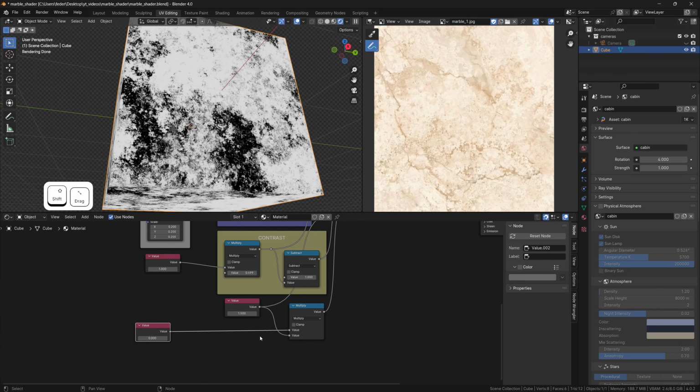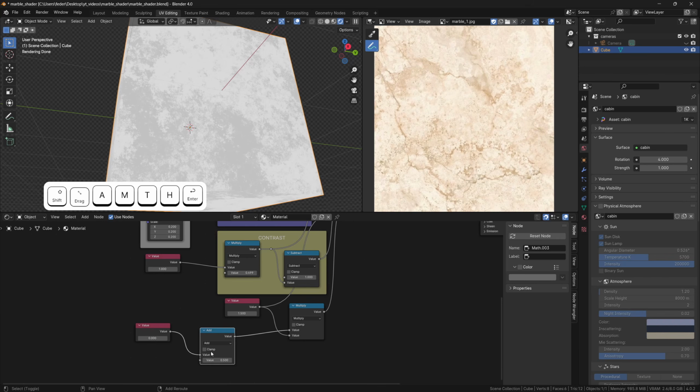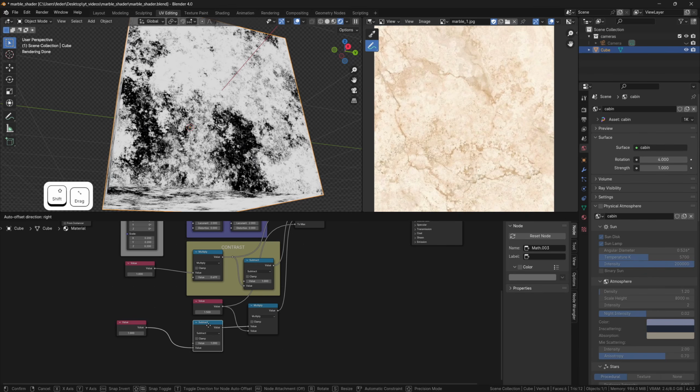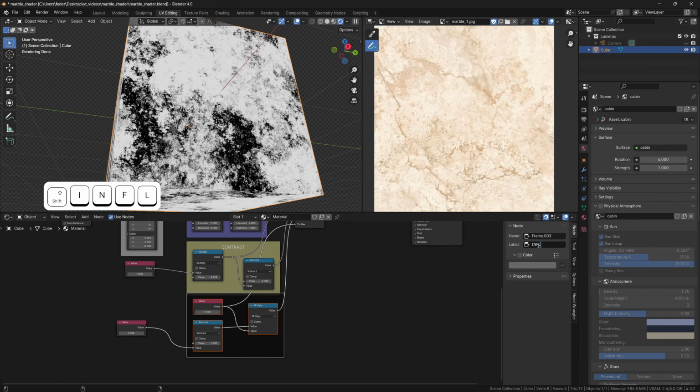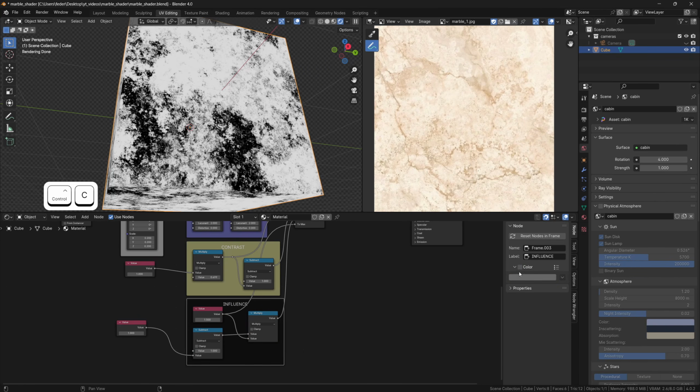But as this is currently doing the opposite of what we need, with 0 being full influence and 1 being no influence at all, we actually need to feed the multiply node the complement to 1 of our influence input value node, which will now make the system work as intended. Again, I'm progressively grouping nodes by their functionality as to keep track of what is doing what, as these trees can get pretty busy quite fast.